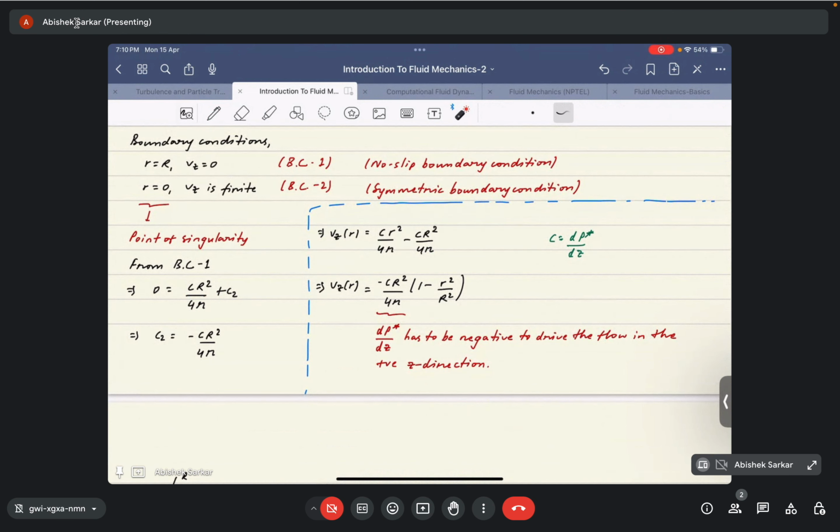Okay, and that's the concept of the existence of a favorable pressure gradient. Moreover, the term favorable pressure gradient is usually used in the case of flow over flat plates or flow over airfoils, where the favorable pressure gradient accelerates the flow, and the presence of adverse pressure gradients decelerates the flow and in fact results in flow separation. But a similar idea can be applied here also.